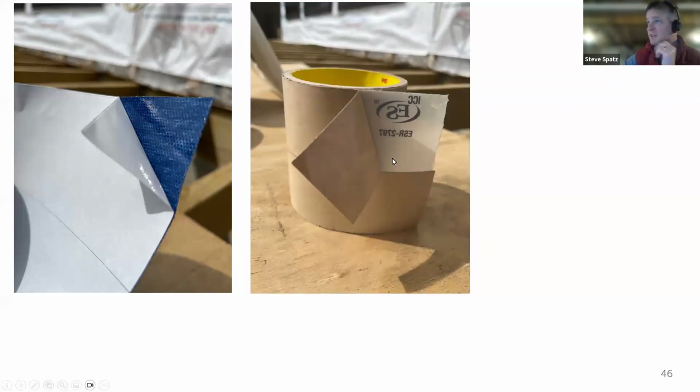So, then we get into some of these other pressure sensitive acrylic sheathing tapes. This is the 3M 8067 weather sealing tape, which I used a lot of. I think it's a pretty universally flexible, literally and figuratively, type tape that can do a lot of different things and be used for a lot of different applications. It's very stretchy, tenaciously bonding. You can use it for a lot of details that in the past you probably would have tried to caulk and it wouldn't have worked very well.